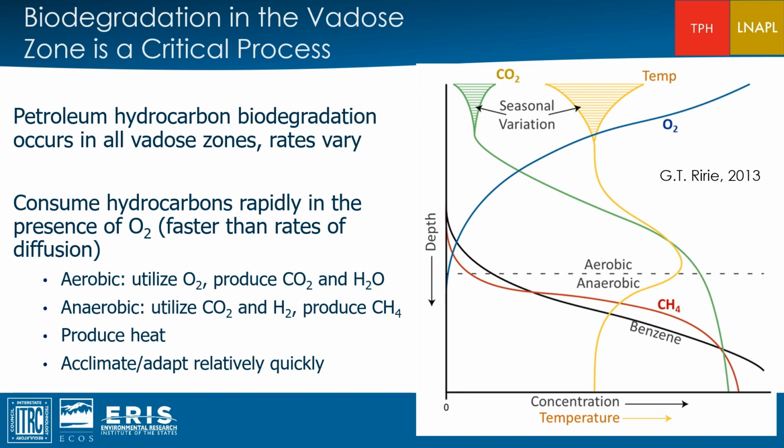The biodegradation of hydrocarbons will result in the utilization of oxygen and production of carbon dioxide. Oxygen will also be consumed in the oxidation of naturally occurring organic matter in soils and the oxidation of methane that is generated by the anaerobic biodegradation of hydrocarbons both in the vadose and saturated zones. In most cases, the methane generated from anaerobic biodegradation will be completely oxidized to carbon dioxide at some distance above the hydrocarbon vapor source.